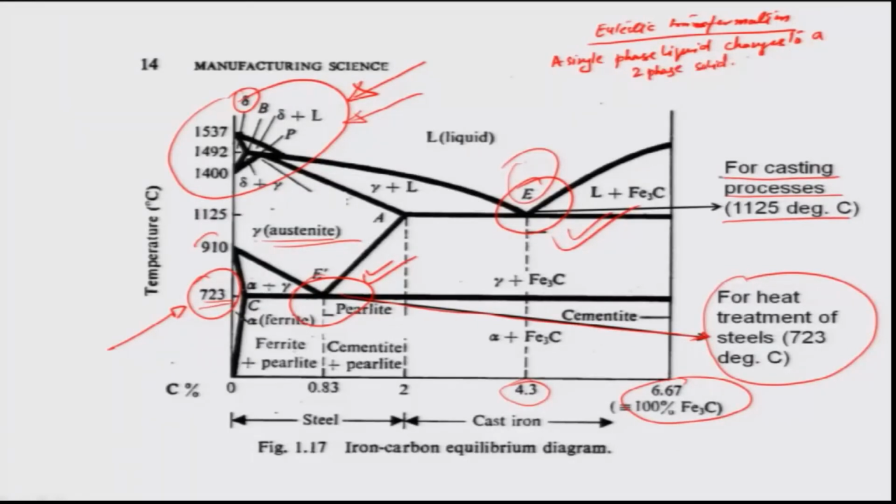If you remember in the ice salt diagram, we talked about salt water which was completely uniform and homogenized, and it freezes below minus 22 degrees Celsius at a certain percentage of salt, and that structure, although not distinguishable, is a two phase structure. So, basically salt is entrapped homogeneously within the ice crystals. That is what the eutectic transformation is.